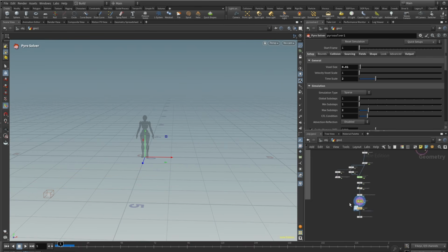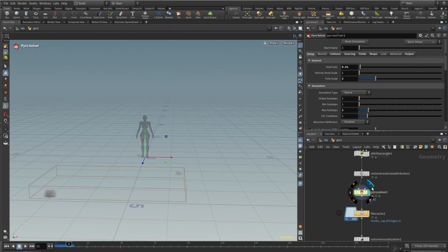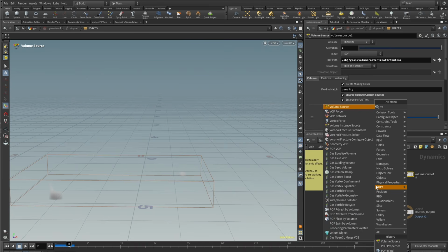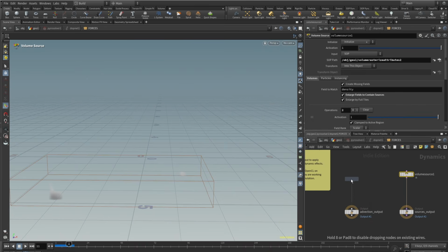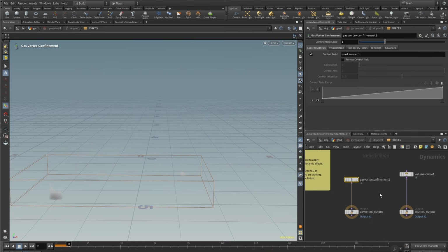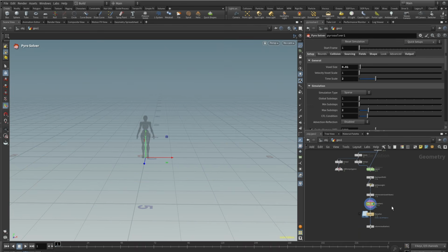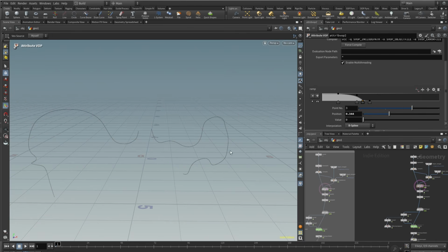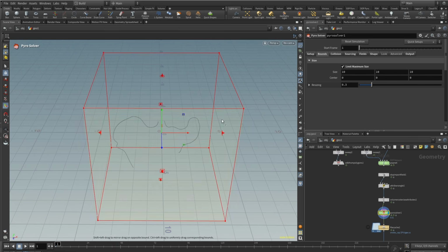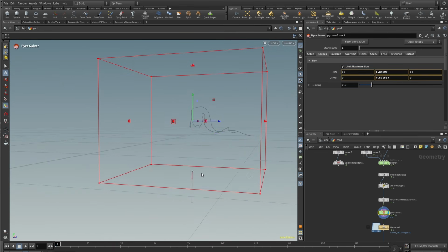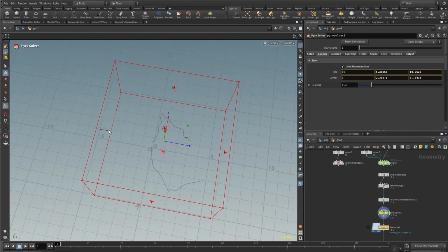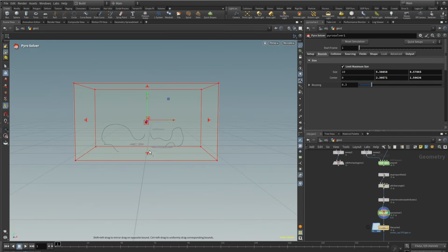Okay, now both emitters are working. As well, let's create a gas vortex confinement. To add a couple more details, I'll set confinement scale to 3. Let's display ghosting for both curves and set bounds for the simulation in case it goes too far, so it simulates faster. I'll set limit maximum size and set container boundaries, and then we can save the simulation to disk.